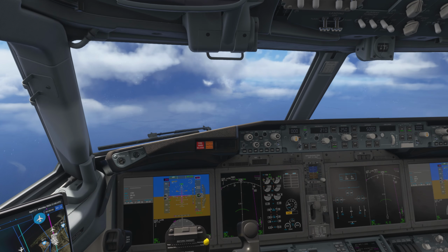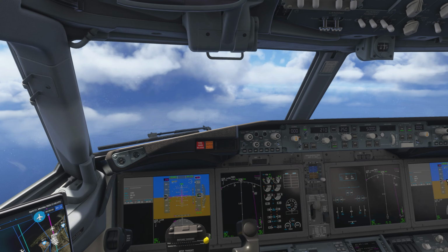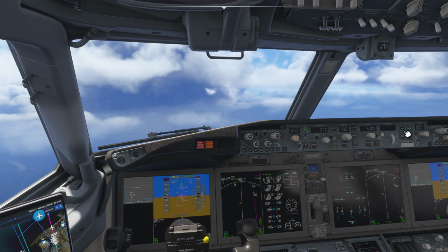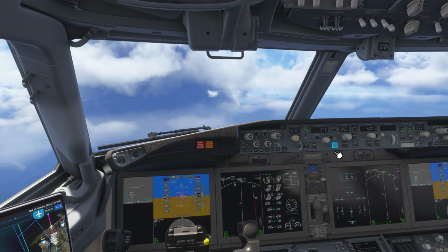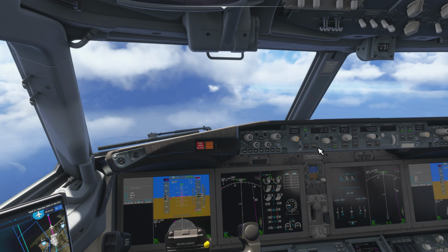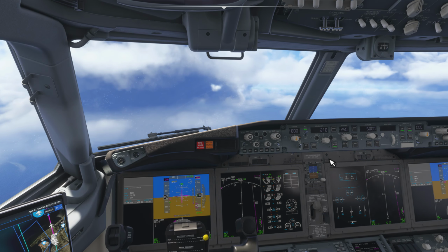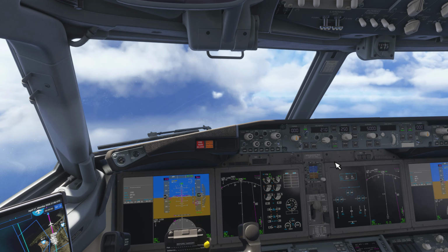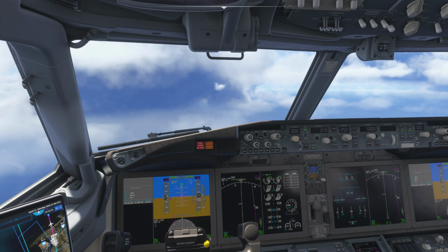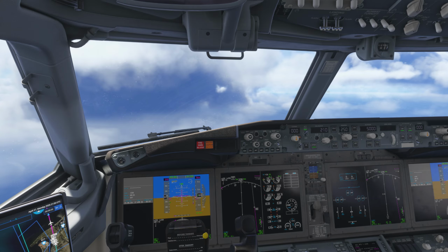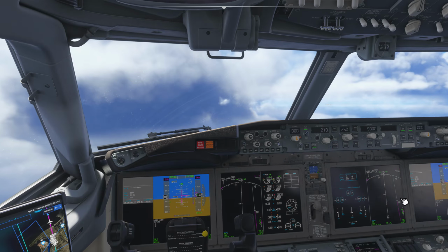Let's just put flaps fully up. So it looks like she's going to head downwards, but that autopilot will usually kick in. Again, activate the autopilot system over here and altitude level change button right there to get that going. Let's make sure our speed, I don't know why, usually stays lit. So, okay, once she gets to the altitude, the level change will go off.